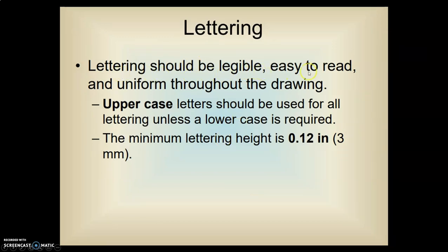Lettering should be legible, easy to read, and uniform throughout the drawing. They should be all uppercase letters. The minimum lettering height is about 1/8 of an inch, or 3 millimeters if we're doing a metric drawing.